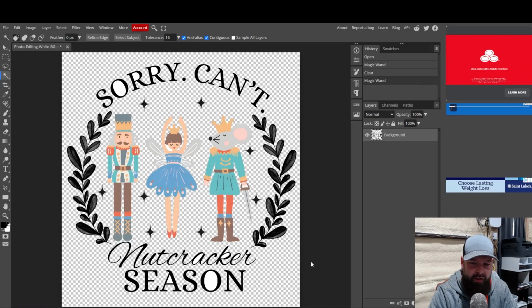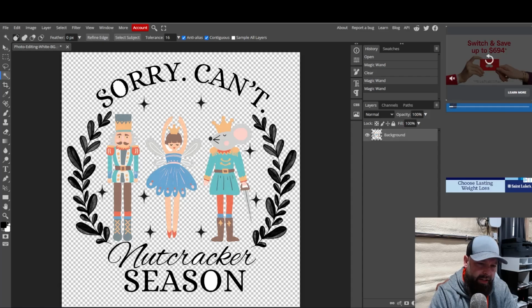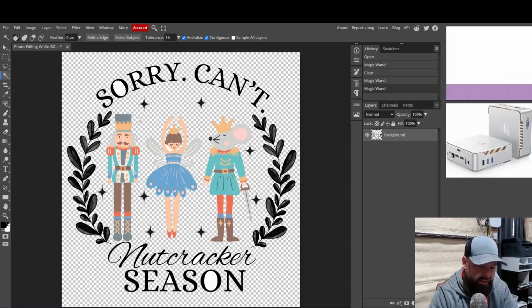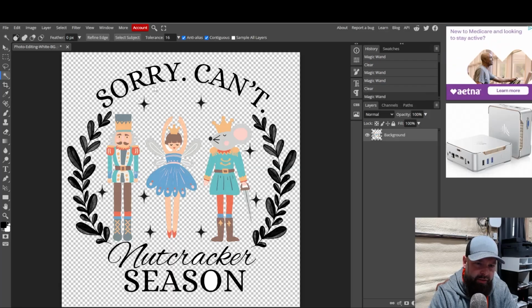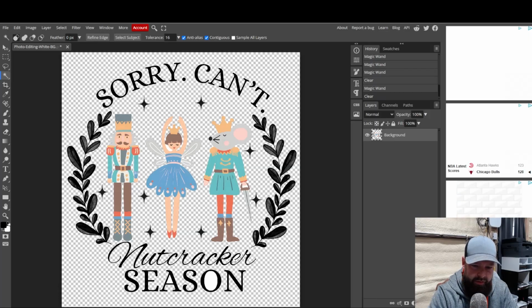As you can see here, there are some outliers that we need to also fix, like this O and in between the R. So you have to pay attention to these details because these will get printed as well. So I'll just select each one and hit the delete key on the keyboard, and we will get rid of each and every one of these. And if you click on something and let's say it accidentally highlights everything like I did, just click out of it and then you can go back to clicking within again. So let's remove each one of these, and we got them.